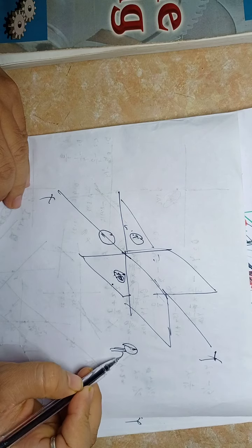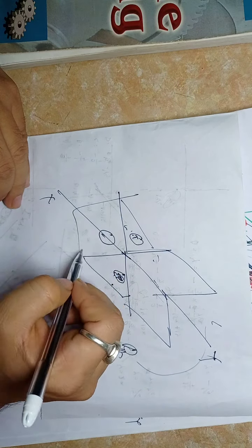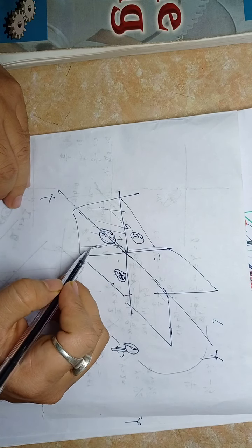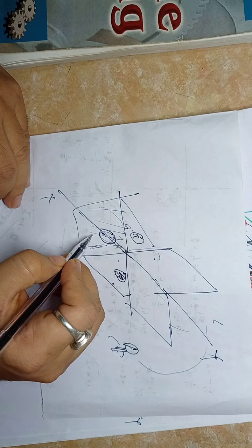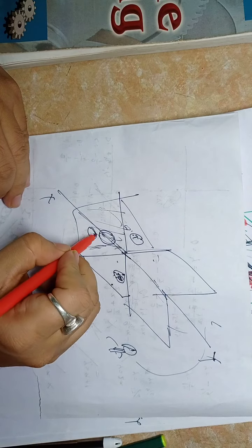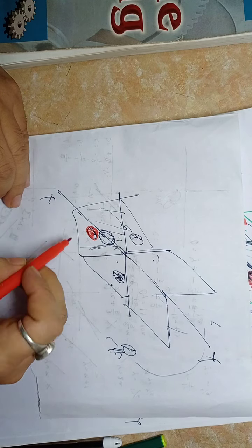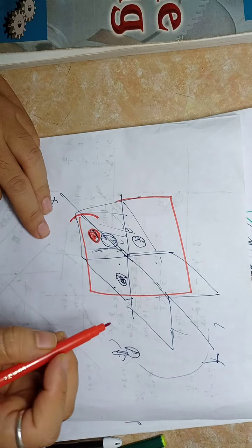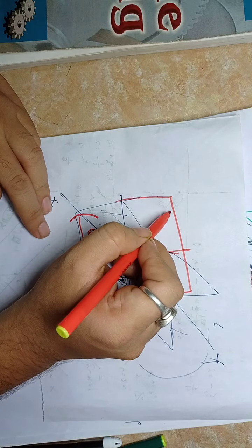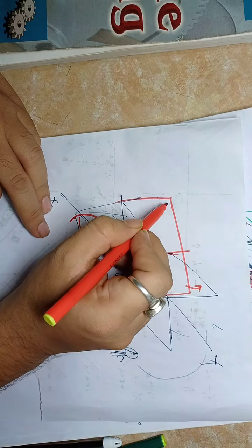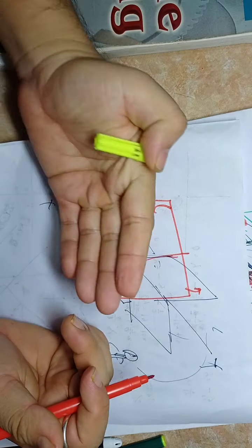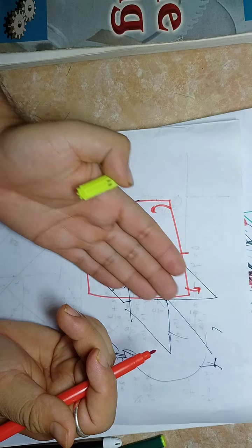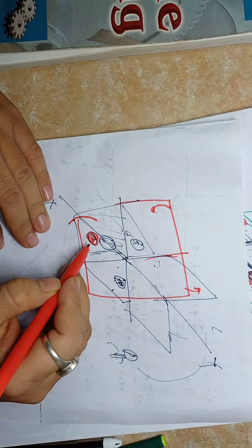Now you're again here, and you'll go that side. You see, this object is actually below the xy line, so your right side view will be here. Let's draw it with some black. This one here, and this is the plane. Now this plane you must rotate in this manner so that it merges with your vertical plane. Similarly, now this is the right side view.